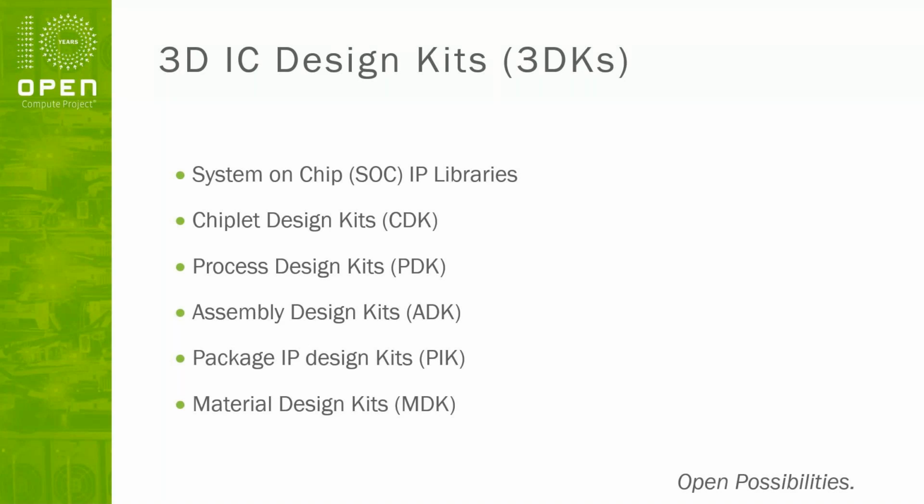I come from the IC world, and typically we're very used to dealing with standardized libraries coming from fabs and such. But in the packaging world, it's a little bit different. Typically, they'll get the information from the vendors about the different connectivity structures, TSVs, bumps, and micro bumps, and then they'll create their own GDS and LEF models for those. But the idea is let's try to put that into a standard set of library and kind of package it up. So it's not so much a standard, but more of a best practice to deal with these common elements.